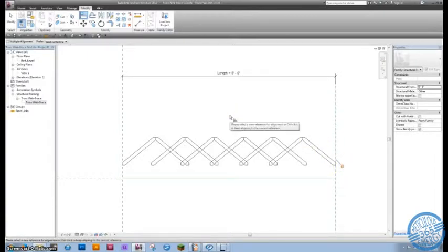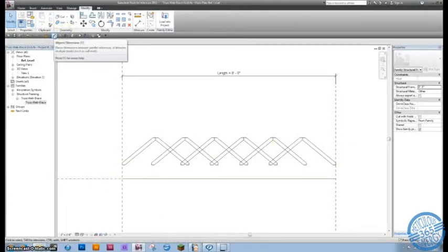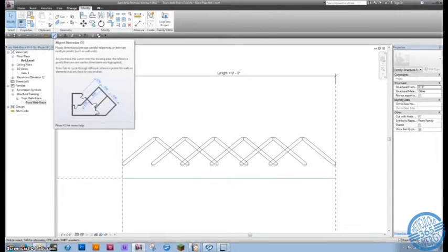So the left and the right are fairly straightforward. They're just simple aligns. The top and bottom, however, are different. The reason that is the case is because the left and right are this group going to this reference and this group going to this reference. So the two groups are going to different places. However, when you're going down, they would both be going to the same reference, and that will give you, or potentially give you, an elements are over constrained error.